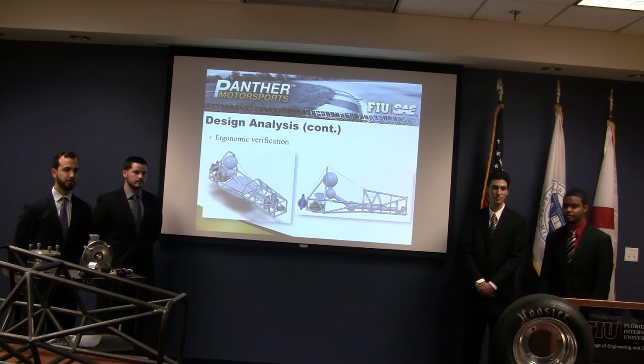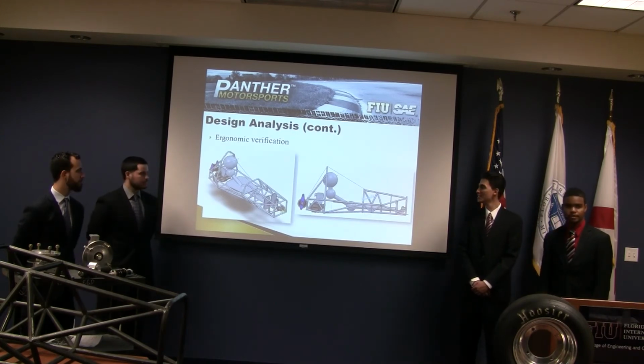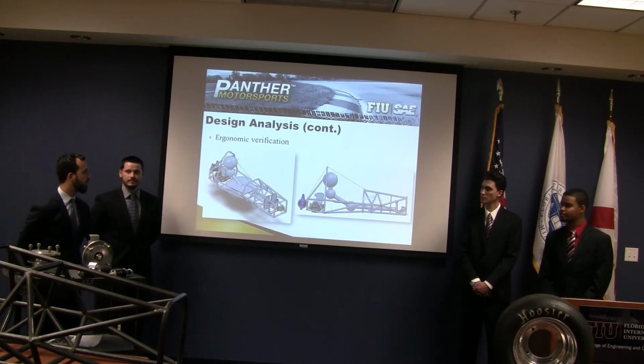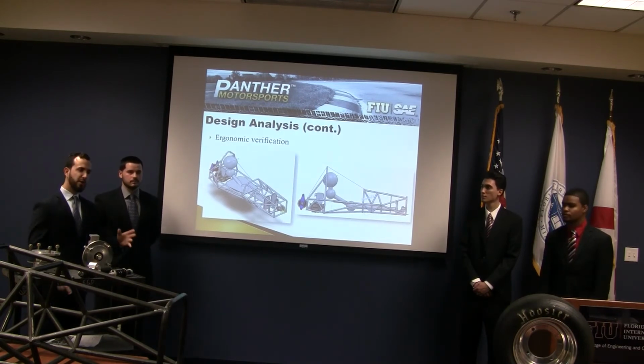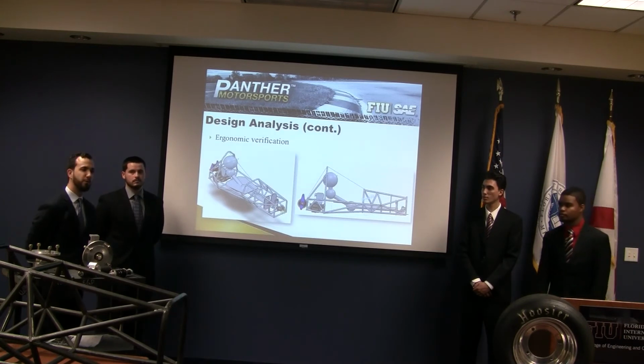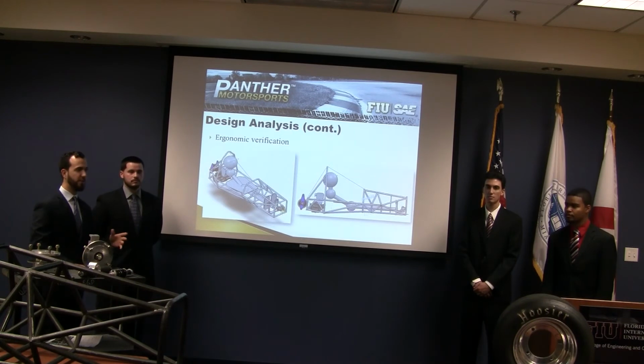How comfortable do you think this seat will be? Because I'm looking at that really low angle, your neck's like this, and you got a big helmet on. You gotta take that into account too. When we do the ergonomics integration portion, we throw a 95th percentile in a somewhat comfortable position. But on top of that, if you open up our paper, we did an ergonomic rig out of wood first, before any of this was present, and sat a few members from the shortest to tallest and took measurements on that jig of wood, and then translated it into what you see on CAD.